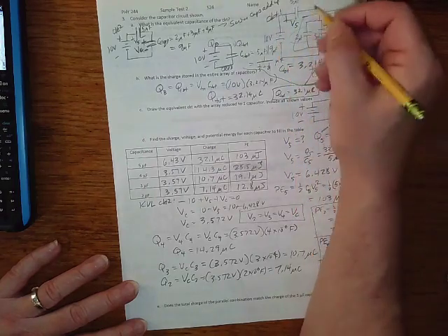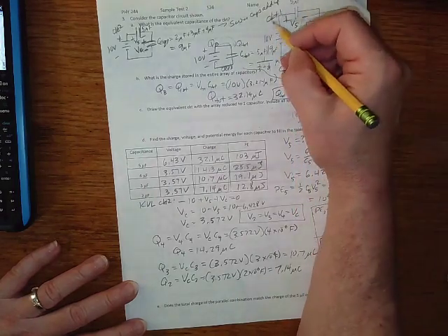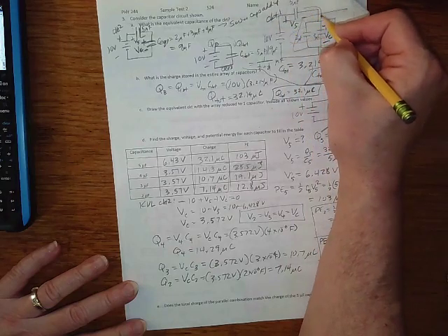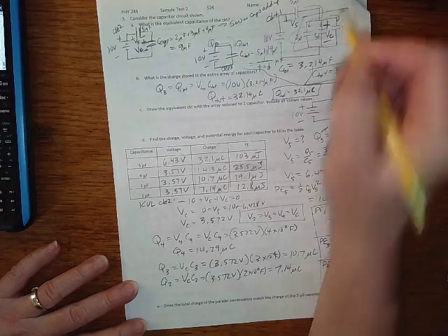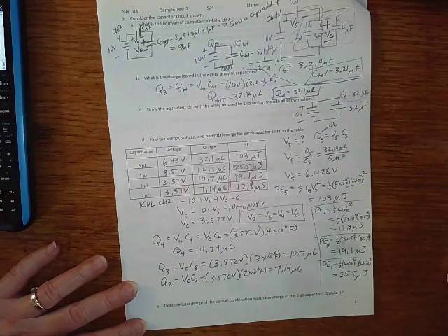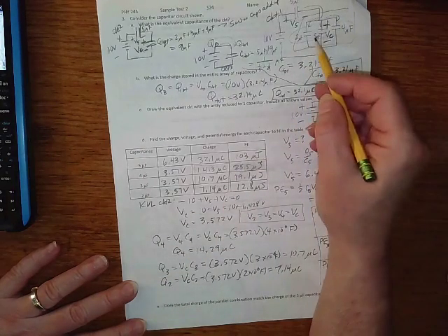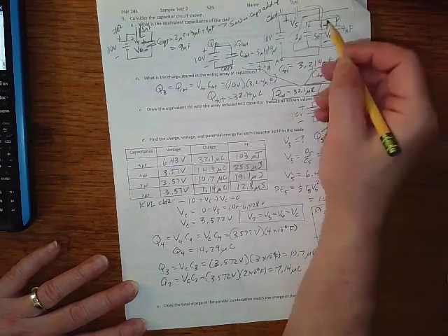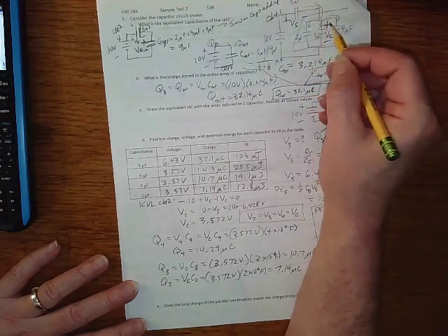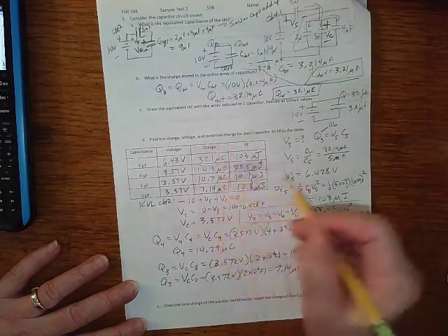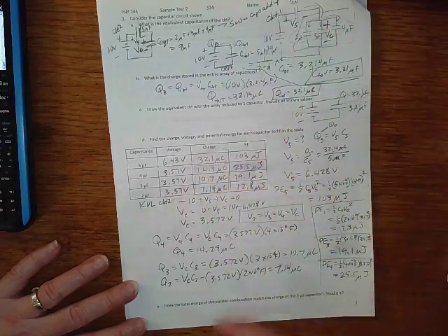So the total charge of the battery comes here, and then it's going to split. Some of it's going to go to that one, some of it's going to go to here, some's going to go to the 4 microfarad. So some to the 2, some to the 3, some to the 4. But the total that comes can't go anywhere else, has to go to those 3. So the total that was in 5 should add up to be what was in the other 3.